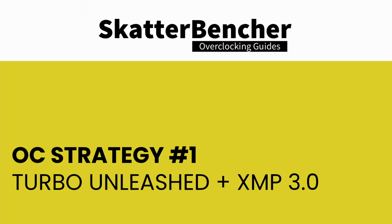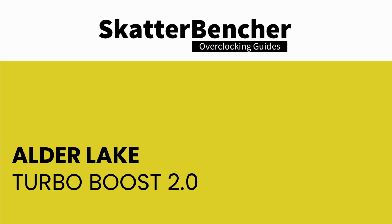In our first overclocking strategy, we simply make use of unleashing the Turbo Boost 2.0 parameters and XMP 3.0. Turbo Boost 2.0 is an Intel technology that's been around since 2010 on Sandy Bridge. Simply put, Turbo Boost 2.0 allows the processor to operate above base frequency if there's sufficient power, current, and thermal headroom. The obvious advantage is improved system performance in both multi-threaded and single-threaded applications.